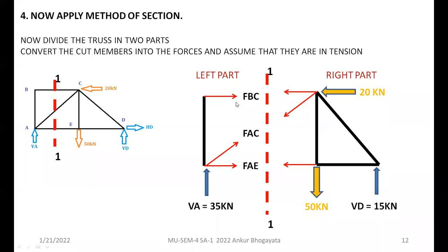You will be seeing that when I cut this truss by section 1.1, all 3 members are being cut. So these members which I have cut, I have represented in form of forces, tensile forces, right? So always remember that when you cut a section and when you cut a member, that member will no more remain as a member, but it will be shown as force.